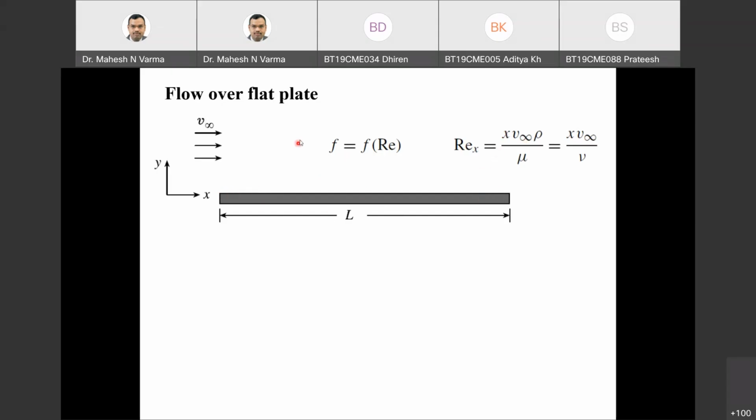So here you can see, for flow through pipes, I can say that Reynolds number of a flow is 1500, Reynolds number of a flow is 5000. But here you can see x. Here x equals 0. So certainly, according to this definition, Reynolds number will be 0 here. Then slowly Reynolds number will increase, and here you will have the maximum value of Reynolds number, keeping all other properties constant. This is bulk velocity, this is bulk density, this is bulk viscosity. Everything is kept constant.